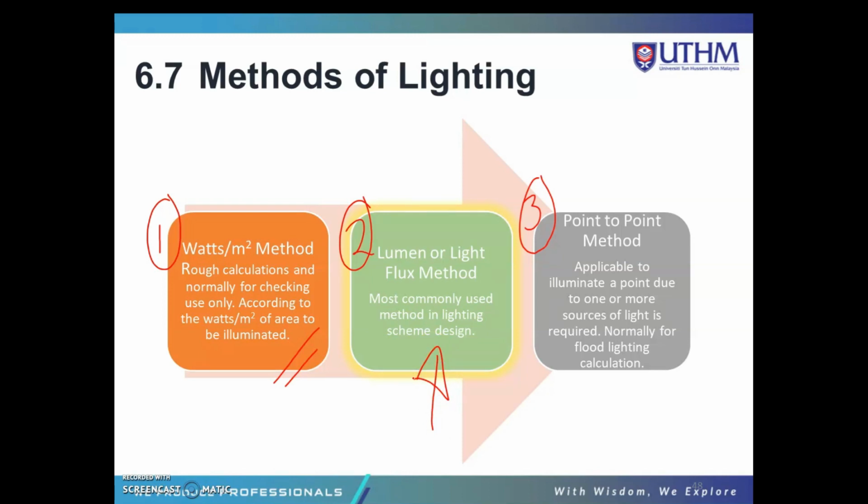Okay, and then the third method is the point-to-point method. This is applicable where the illumination of a point due to one or more sources of light is required, normally for high intensity artificial light such as floodlight calculation.